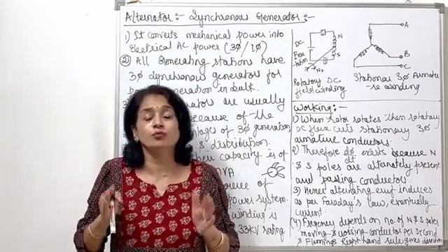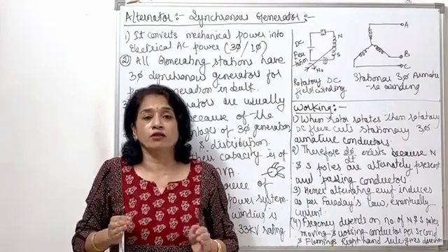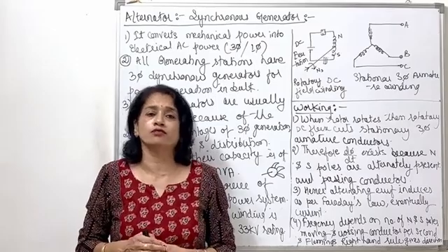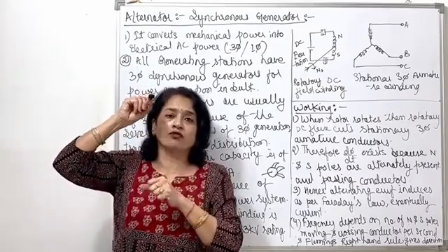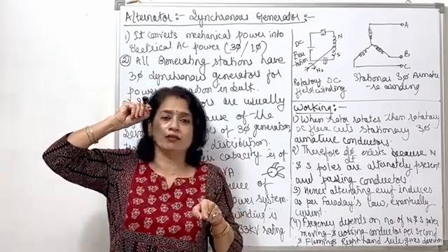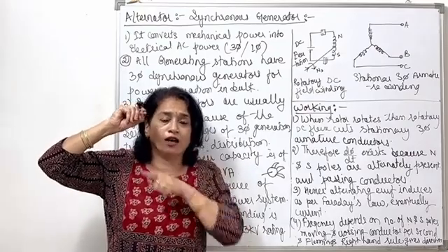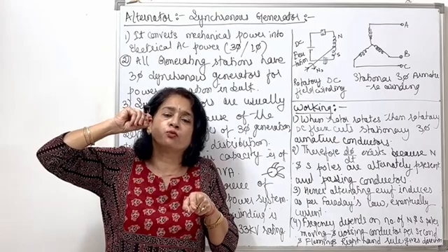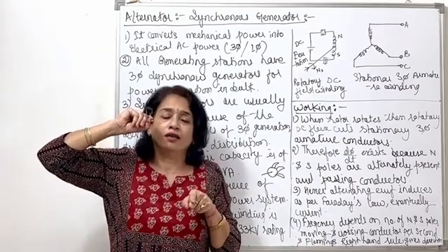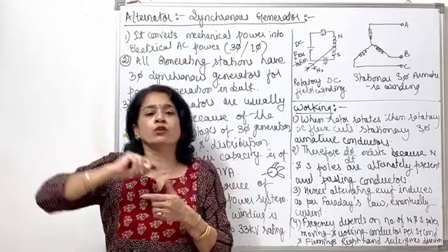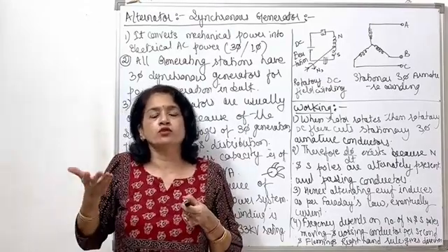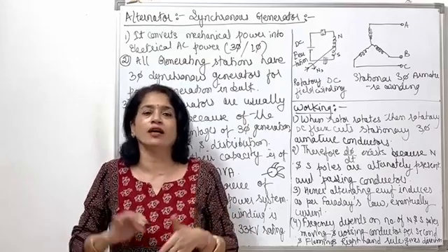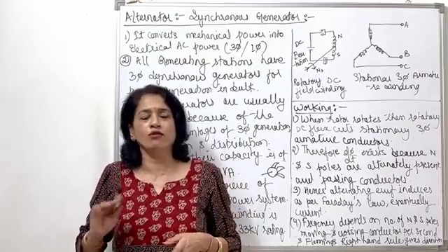What does this mean? It means AC power generation is there: AC EMF is induced, because of which AC current flows. This conductor is of A phase, so 120 degrees later, mechanically 120 degrees after, this particular conductor also has the impact of the north and south pole, but lagging by 120 degrees. C is also impacted by the north and south pole, but with a 120 degree phase difference with respect to B. It would lag the B phase EMF and B phase current by 120 degrees.